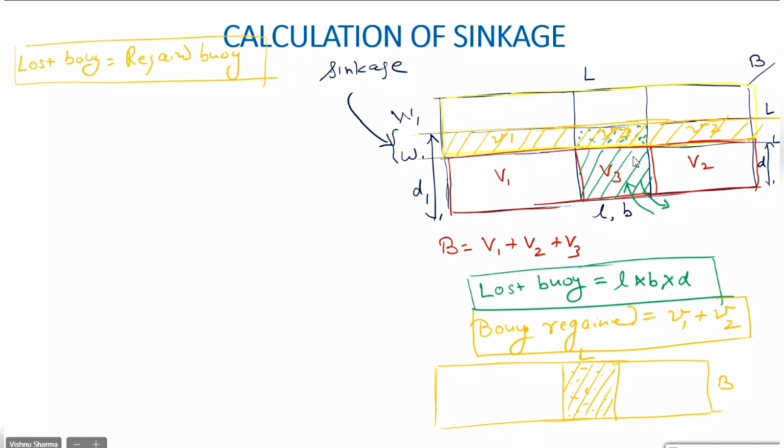We said wherever you can't see the sea water, when you look from top, the area which displaces the sea water is the water plane area. But when I see from here, what do I find? That in the middle, a certain area is occupied by sea, and under the lost buoyancy method, that water belongs to sea. Yes or no, guys? Yes, sir.